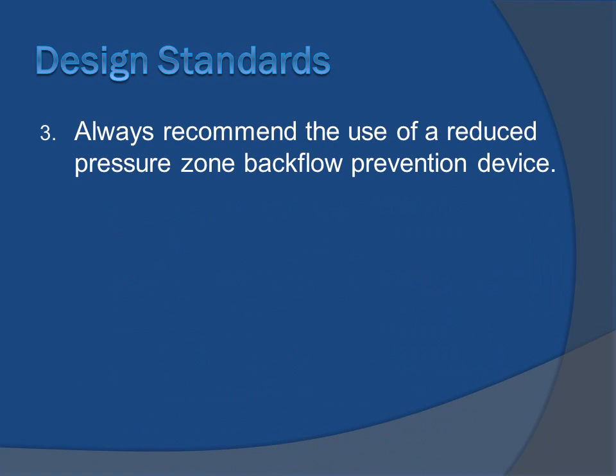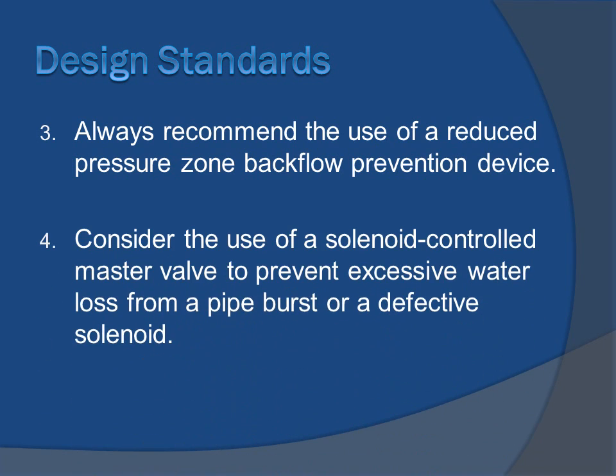Always recommend the use of a reduced pressure zone backflow prevention device. And consider the use of a solenoid controlled master valve to prevent excessive water loss from a pipe burst or a defective solenoid. Alright, so right there what they're talking about, the master valve is something that you can turn off. And they're saying using a solenoid control, so it's actually connected to the system.